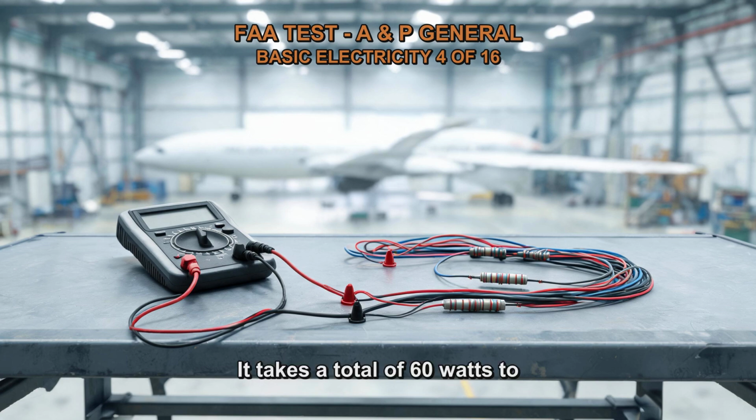It takes a total of 60 watts to power the 3 position lights. 120 watts are required for the heating element. 72 watts are needed for the anti-collision light. The generator must generate a total of 451 watts.